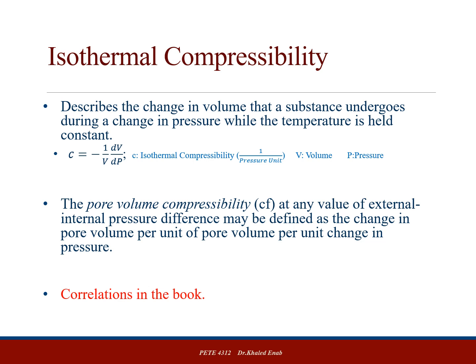So the next property we need to consider is the isothermal compressibility. Isothermal compressibility simply describes the change in the volume that a substance undergoes during a change in pressure while the temperature is held constant.